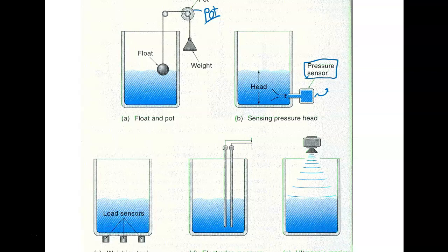But we used capacitor probes. So every time we replaced the probe, we had to recalibrate the fuel system. We had to recalibrate because there's no way in the world two probes could be exactly the same. Right. That'd be like all the cars out in the parking lot having exactly the same mileage on them. What would be the odds of that?